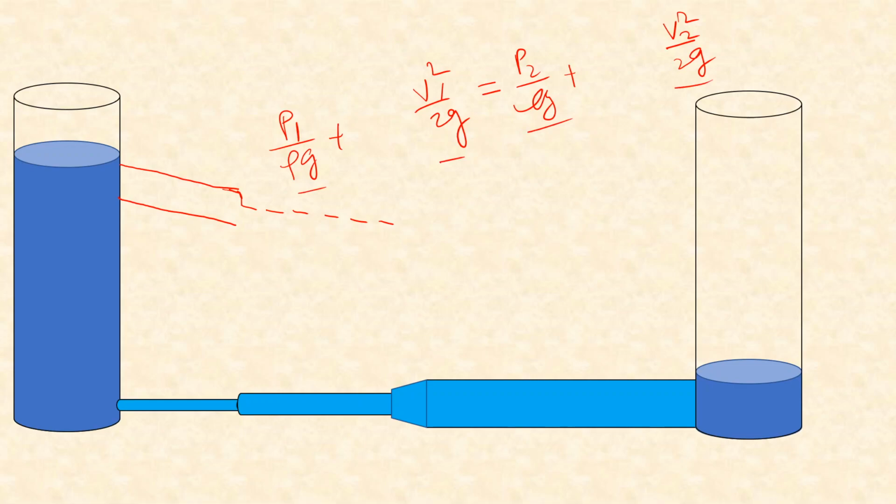If V is decreasing, then P must increase. And that's what is actually happening in this case, where in a larger diameter pipe, pressure will increase, but the velocity will decrease. And that means, although the total energy is obviously decreasing because it is being lost, the hydraulic gradient line may not be falling like this. In some cases, it may rise up.